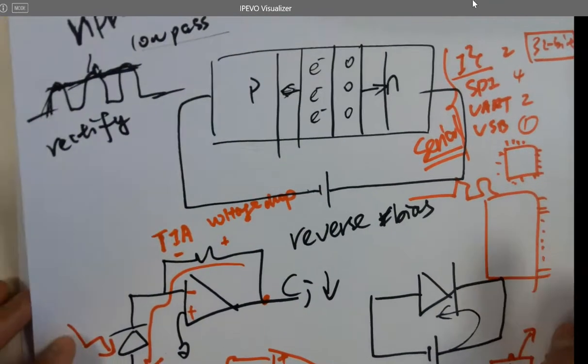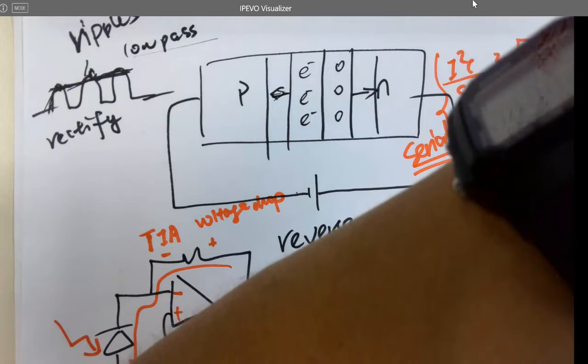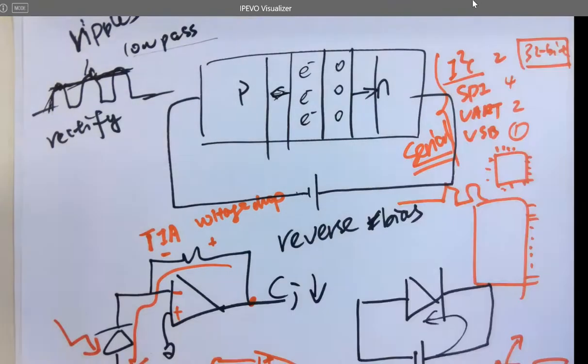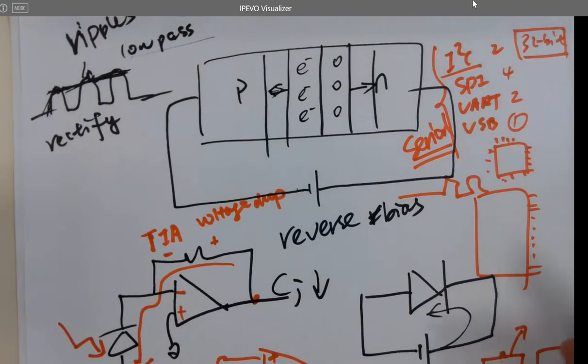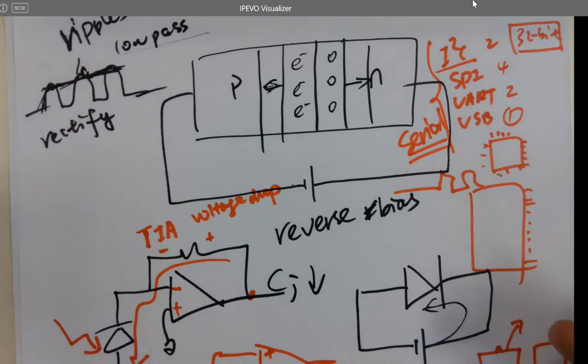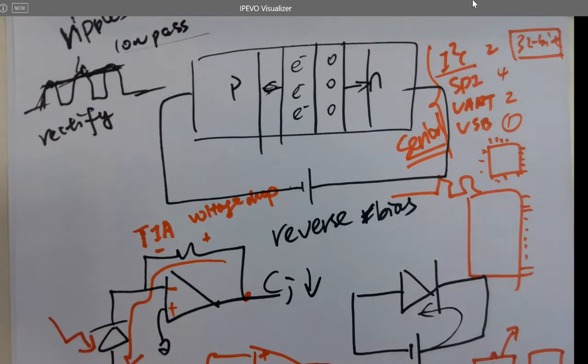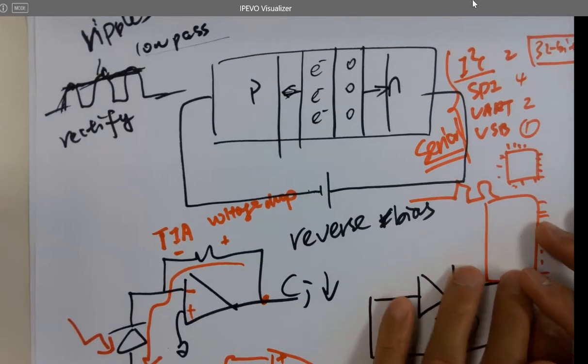So the place we can use parallel communication is still not directly for the IOs of the chips, but inside the chip. You can have 1,000 wires inside the chip, right? For internal communication, if you use parallel, it's going to be a lot faster than serial. They don't use serial internally inside the chip, like FPGAs. You have the internal wires. Remember, you can define a wire with 8 to 1 or 31 to 0 or something. So these are all parallel buses, which will be fine because it's faster and direct. Usually, if you have a wide data type, they will be able to send all the data at once through one clock. So all these in-chip communications are still parallel. But all these external pins are serial for the modern communication with modern digital chips, right?